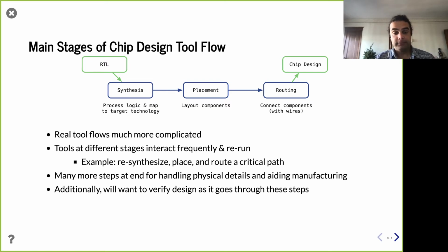I've been mostly talking about the RTL level, of how you make sure your design is easy to test at this level. But there are all sorts of ways, not just for test, but they can also think about, if I design modules in a certain way, I can formally verify not just the RTL, but perhaps the RTL mapping through the various stages, right? Proven equivalence check between what was produced by the tool after optimizations versus what came in.